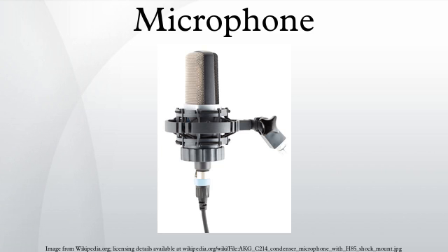A small movable induction coil, positioned in the magnetic field of a permanent magnet, is attached to the diaphragm. When sound enters through the windscreen of the microphone, the sound wave moves the diaphragm. When the diaphragm vibrates, the coil moves in the magnetic field, producing a varying current in the coil through electromagnetic induction. A single dynamic membrane does not respond linearly to all audio frequencies.